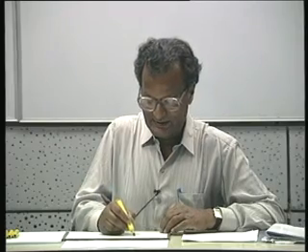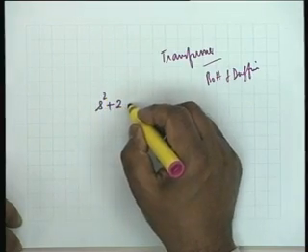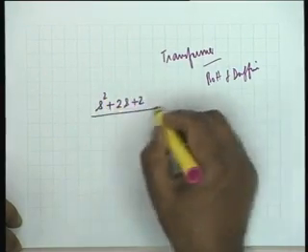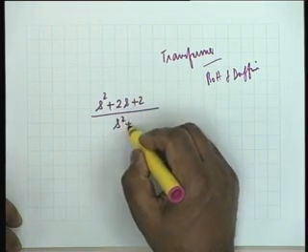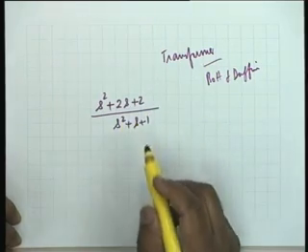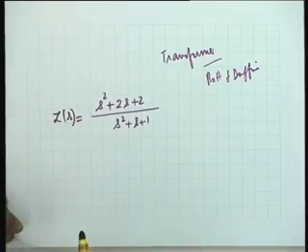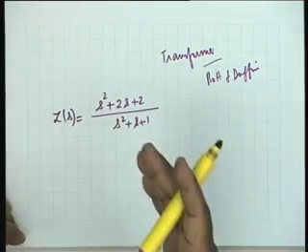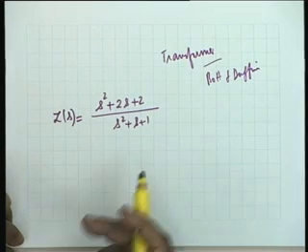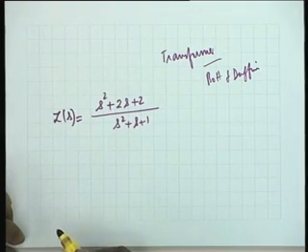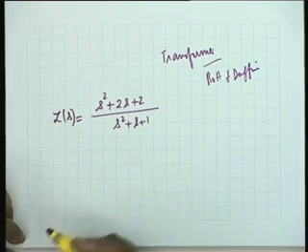That's it. Okay. One of the examples that I take first is s squared plus 2s plus 2 divided by s squared plus s plus 1. You see that if this is an impedance function, the poles are neither on the imaginary axis nor on the real axis. They are complex, and therefore, if at all realizable, it should be realizable as RLC.